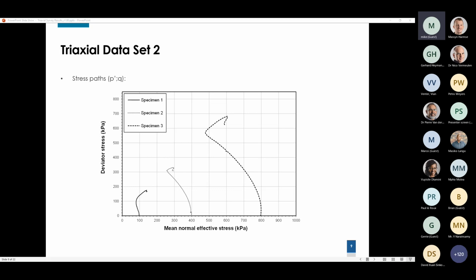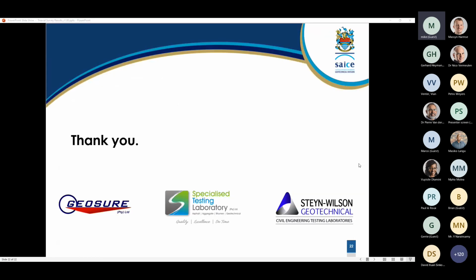Fantastic talk. Just an observation and then two questions. The first one is that we spend a lot of time looking at computers and test results, and the guys tend to forget to look at what's actually evident in the field. By way of just two little illustrations, I've seen analyses of slope failures where guys are taking test results and they'll give you zero cohesion. You say, well, but go out on site, there's a 5-meter vertical face standing there. Don't tell me it hasn't got any cohesion.